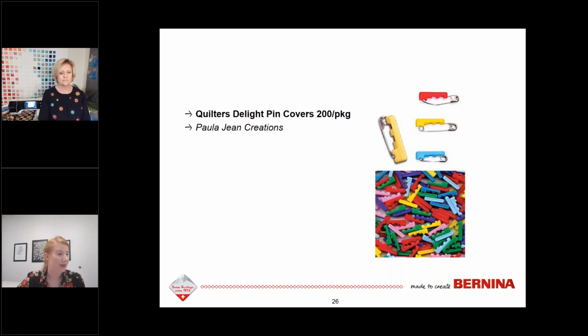Okay. Scroll down here. How would you manage your thread tension on an 880? On the 880, it does not need the high tension bobbin case, and you can adjust the tension right in the hook system. And so, yeah, it's best to look that up in your manual, but you can adjust the bottom tension right there in the machine. And you can also just adjust the top tension. I would always start with adjusting the top tension before I would look to going to the bottom.